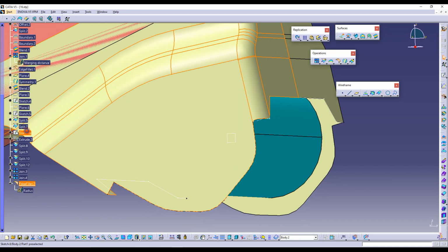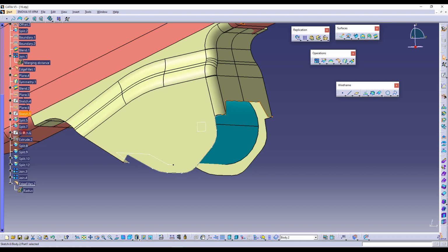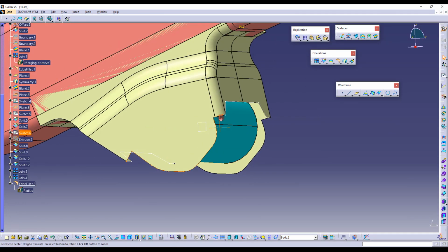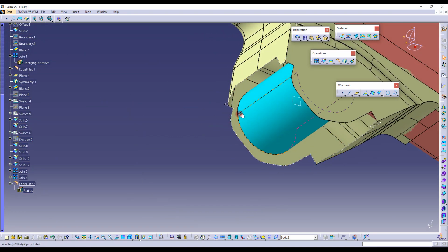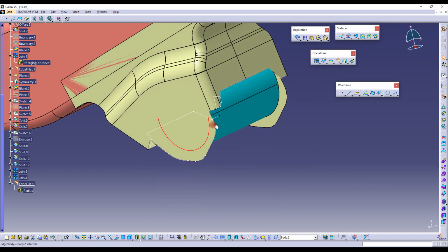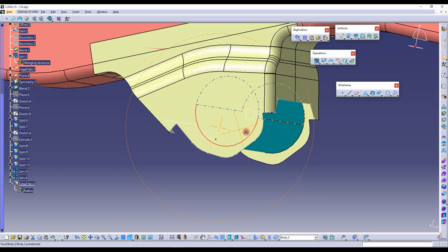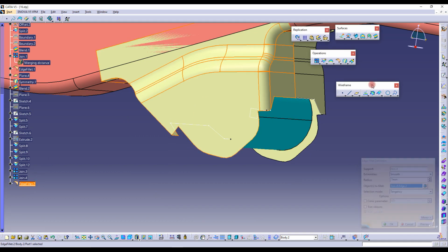So when we give 7 mm, it's going to ride on top of this. So for that, we need to modify that sketch. Not this one, but this one. So just bring this up, increase this. So that should do it. So this sketch is constrained by this edge of the bush. So it should not intrude into this edge because the butting face is required for the bush. So this is the fillet which has been given 7 mm.